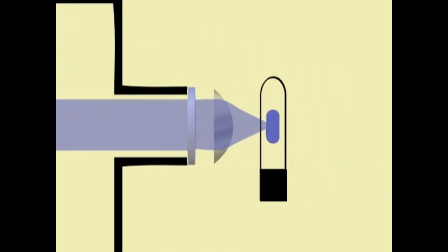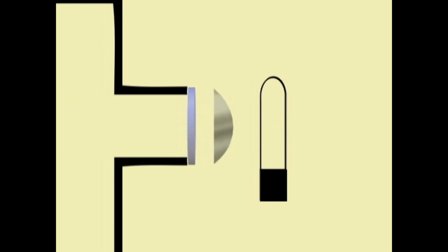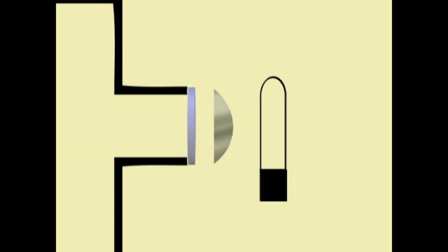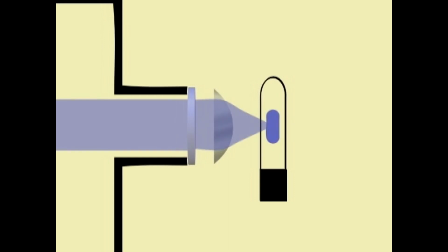The UV lamp is pulsed at 25 cycles per second. The purpose of this is twofold. The primary reason is that this minimizes the effects of any ambient light that may be introduced into the process. Secondly, since our resulting signal voltage will be AC, the effects of noise in the electronics are also minimized.